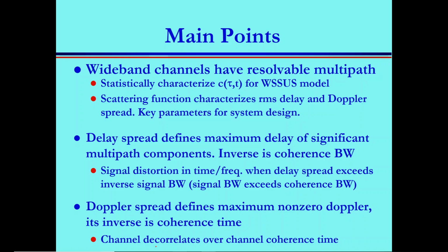Wideband channels have resolvable multipath, and statistically characterize the time-varying impulse response of the channel for WSS-US, wide sense stationary, which means zero mean and autocorrelation not dependent on time, dependent only on the difference.